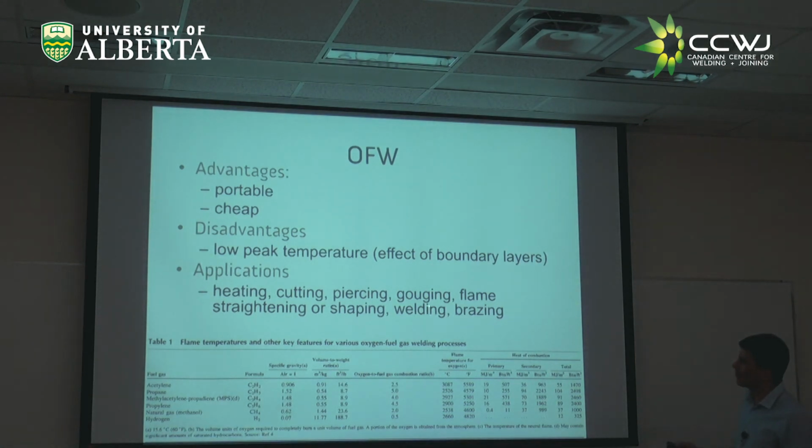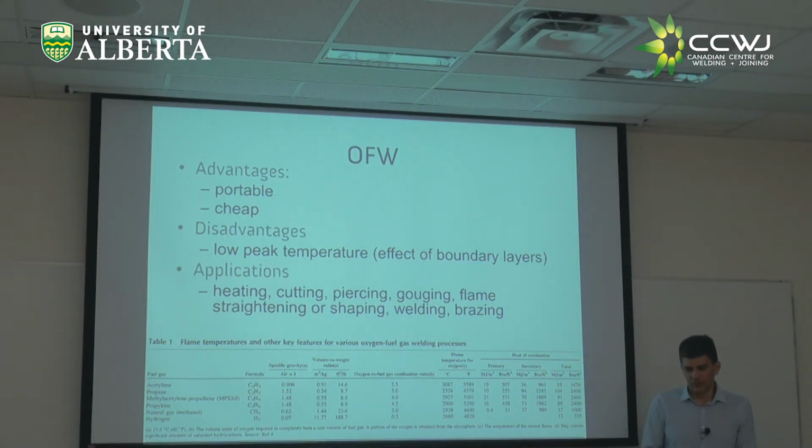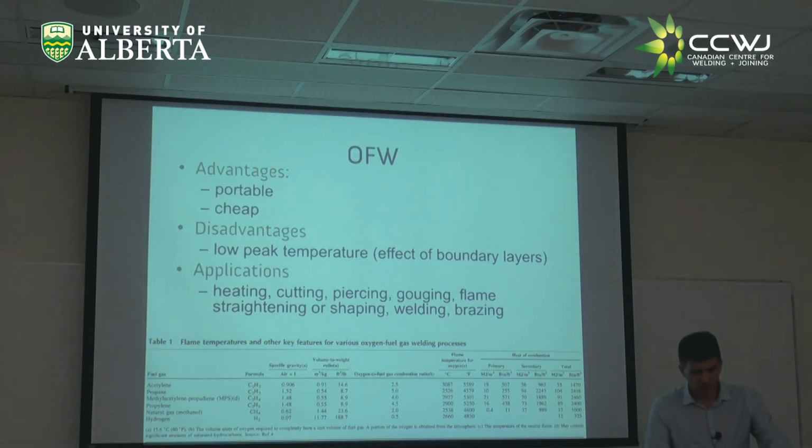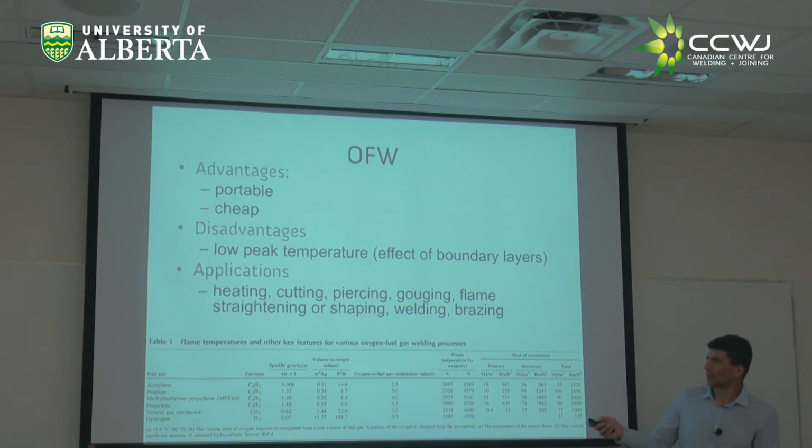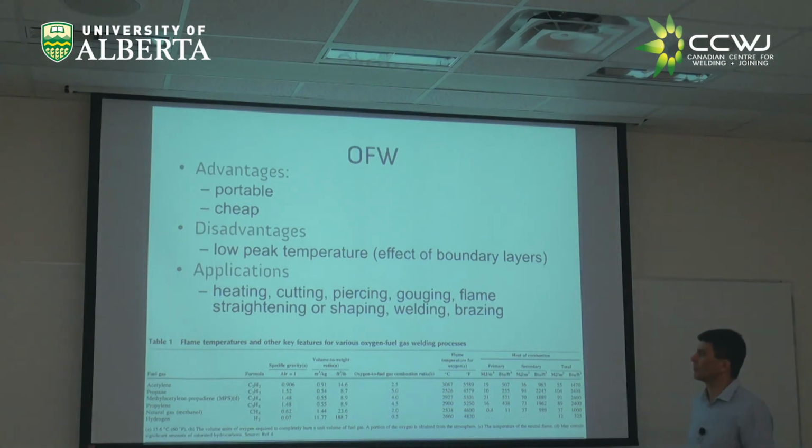Applications. Not only can you do welding, but because the heat is diffuse, you can use it to do preheating. You can use it to do the shaping, right? If you heat on one side of a plate more than the other, this is going to expand and start bending. That's the way you shape the steel sheets in ship making. Like the hull is round, especially as you come towards this bulge under the bow. You know, right? Like the ships have this big bulge. How do you make it all round? Well, with things like this, with flame forming.